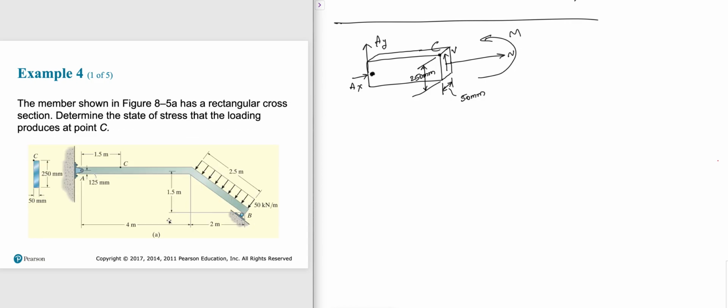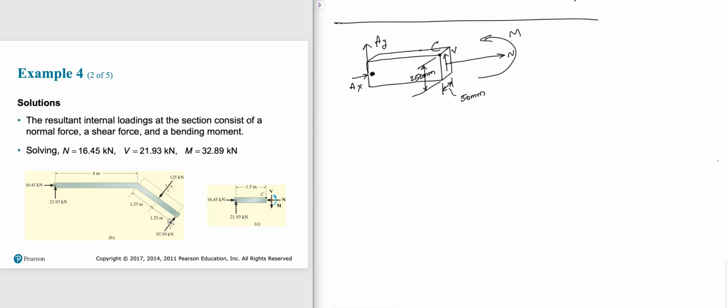And here, this is a roller support. That means you draw a normal reaction that is perpendicular to the roller support, and that's how we have to represent a normal reaction here and AX and AY there. Once you write this, you take a free body diagram and you write sigma Fx equal to 0, sigma Fy equal to 0, moment with respect to this point equal to 0, and then by solving you will find these reactions. And our goal is to find this AX and to find AY. And I'm not showing you how to do this because, like I said, it's a statics problem.